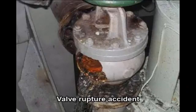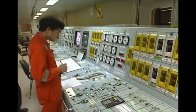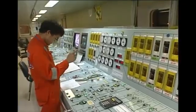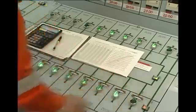In this accident, corrosion in the valve body, combined with sudden pressure change due to pump stopping, ruptured the valve body during a stroke to produce a hole in it. To prevent such accidents, you must have a good understanding of the procedures for proper handling of pumps and valves.